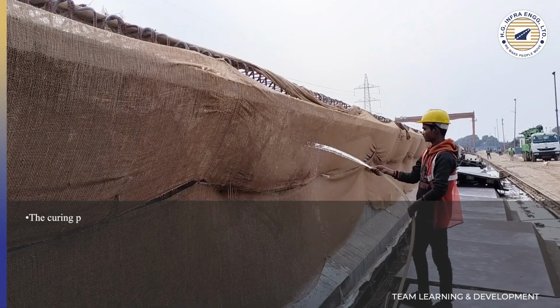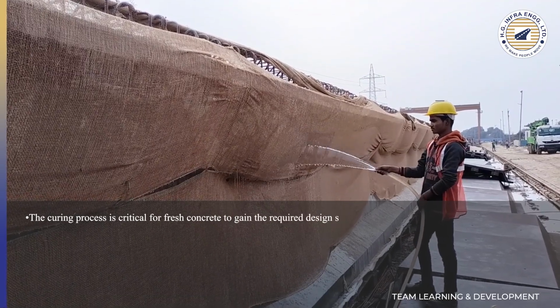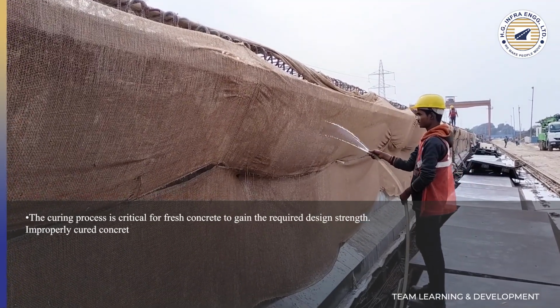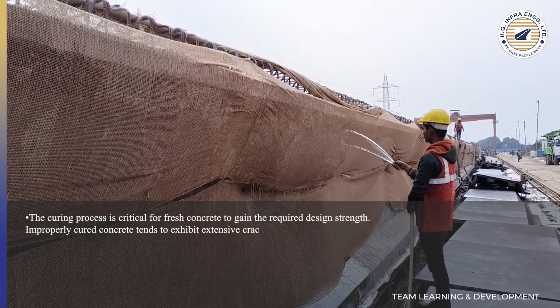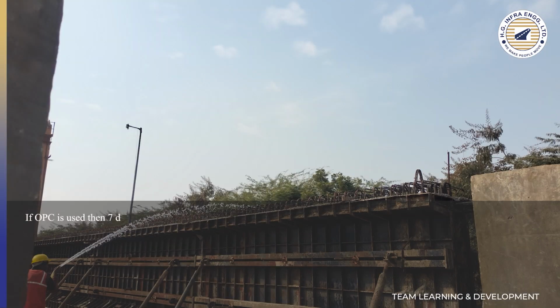The curing process is critical for fresh concrete to gain the required design strength. Improperly cured concrete tends to exhibit extensive cracking due to shrinkage. In case OPC is used, a minimum of 7 days of curing is required. In case PPC is used, minimum 14 days curing is required.